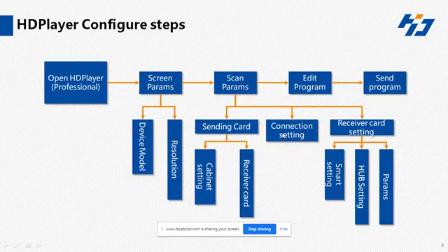In the connection setting, we guide the software on the sequence in which we have connected the receiving cards, assuming that maybe you are in front of the screen or maybe at the back of the screen, and how you have given the connection of LAN cables from one receiving card to another.